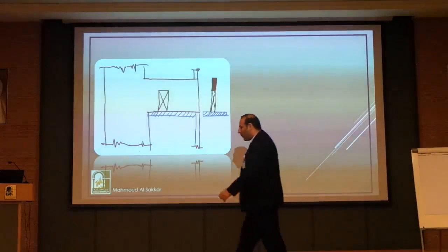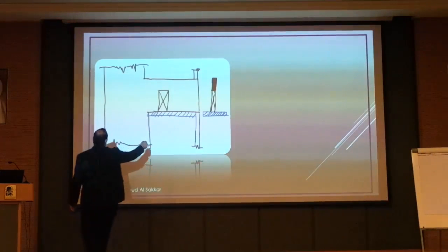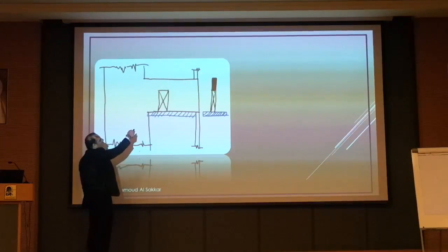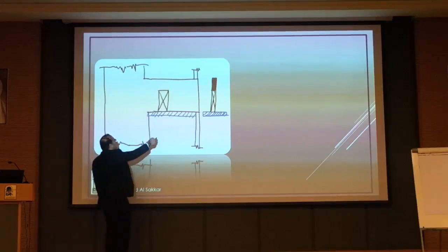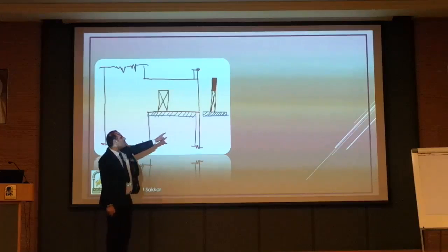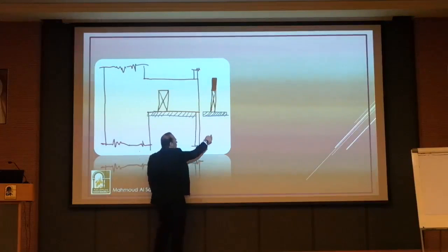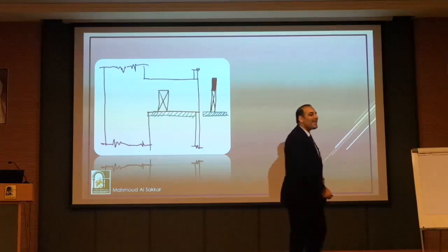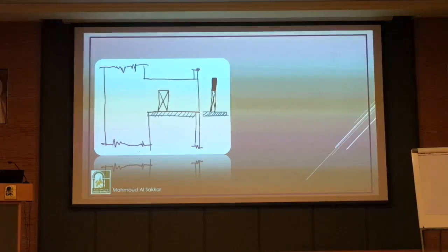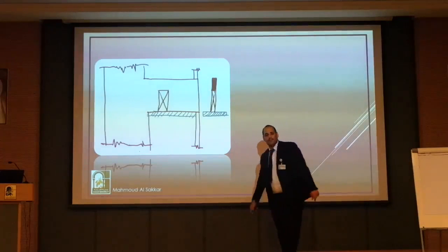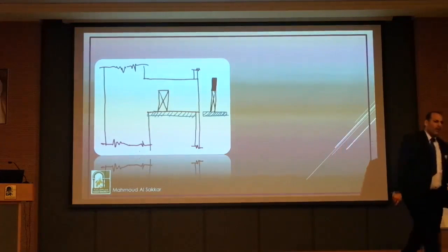For the moment problem, very simple, because here I have a compression zone; the moment is going to make compression and tension, two flanges. I have a big compression here, 1.2 meters or more. And what about tension? There is nothing in tension. So I'm going to use the slab itself as a tension member. The slab is not going to be 20 centimeters here, but I'm going to make a portion of it, for example 60 or 80 centimeters, a big portion. I'm going to take a part of the slab and make it a tension member and increase the amount of reinforcement in it for tension. The other one is going to carry compression. So I have a release of force in this section: compression here and tension over there. Clear? Okay.